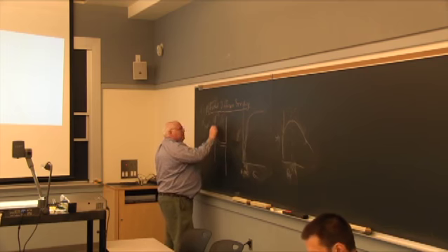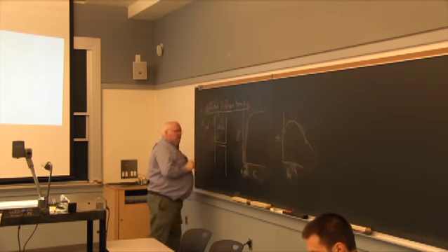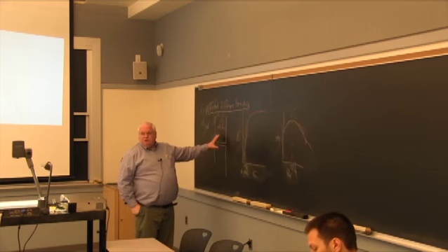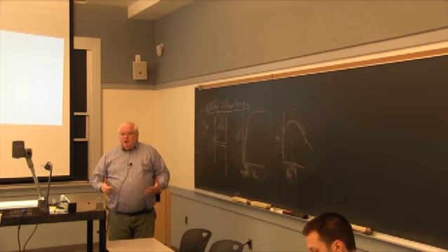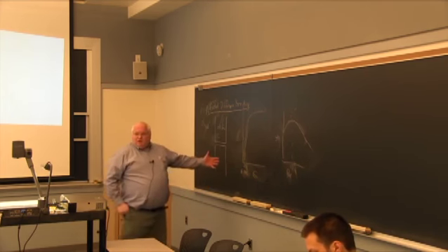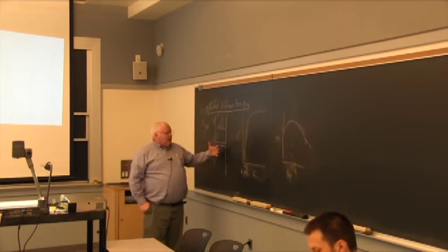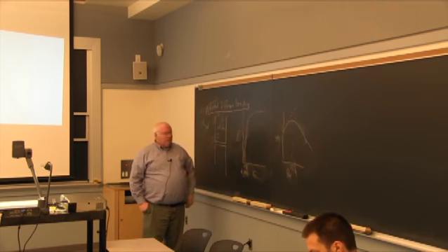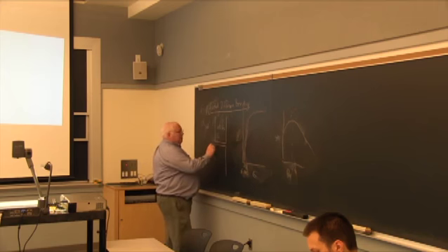They had very high strength maraging steel, so 200 KSI steel, and they wanted to bond it, but the problem is you can't form a diffusion bond at low temperatures. If you go up very high in temperature, these maraging steels lose their properties. In fact, that's one of the problems of diffusion bonding. I said you get a near perfect joint, but you can't always get the microstructure you want. Okay, I heat treat a steel and I make it martensitic, and then if I go up to 1200 degrees to diffusion bond it, it's no longer martensitic and I lost its strength. So you can't always keep your properties.